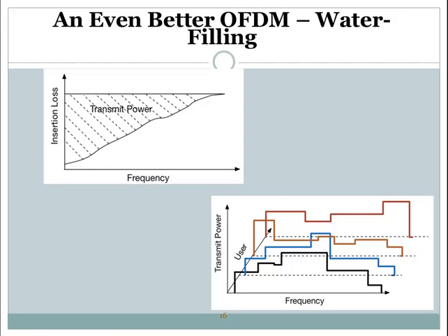Moreover, the Ethernet cable has four twisted pairs, so we can take advantage of multi-user diversity. Each user has its own direct channel, with its insertion loss and return loss, and they have different coupling levels with each other.